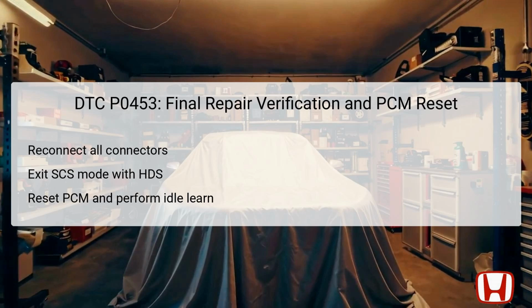The final step consolidates all repairs and confirms the system's proper operation. Reconnect all connectors securely, ensuring no wires are pinched or improperly connected. Using HDS, exit the Special Control System mode to return the vehicle to normal operation. The next crucial step involves resetting the PCM, which clears stored DTCs and allows the system to reinitialize with the new or repaired components. Once the PCM is reset, perform the idle learn procedure as specified by Honda to ensure optimal engine idling and sensor calibration.